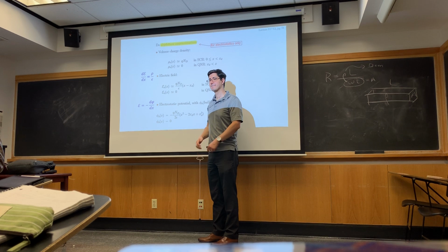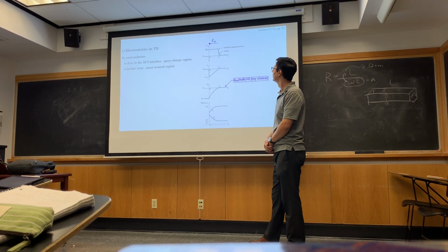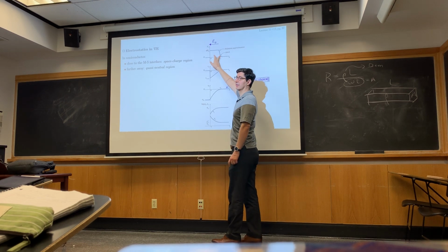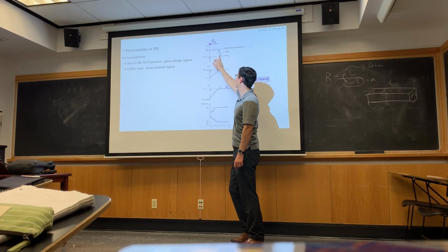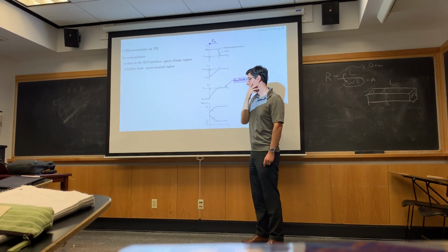Yes? So the previous graph, this is the depletion region assumption between the metal and semiconductor, right? Yeah, we're assuming that we're solving the semiconductor region, assuming the depletion approximation. So the blue curve right here is like the exact, if I were to take the exact profile, but here I'm just making it a rectangle to make all my things easier, right?